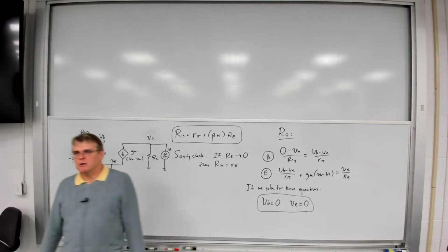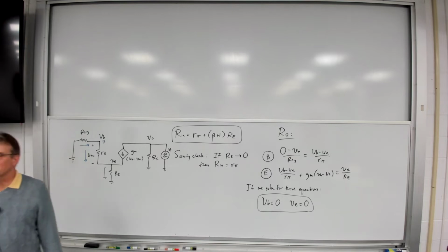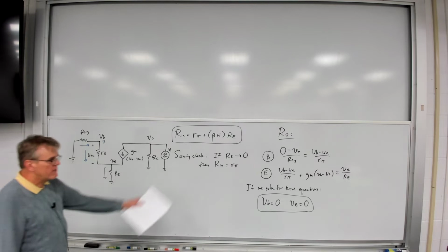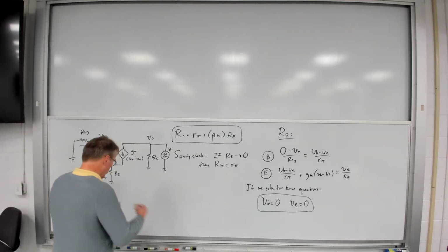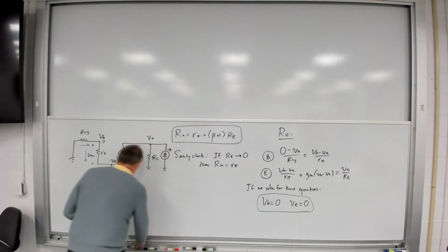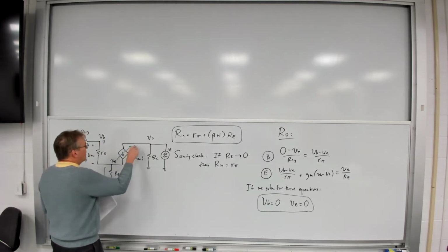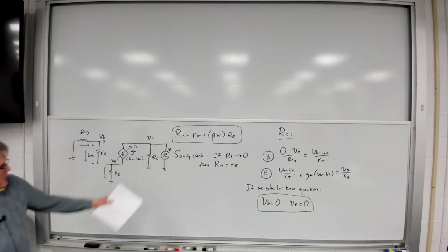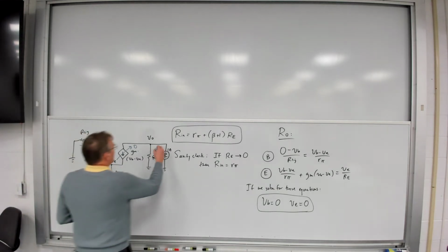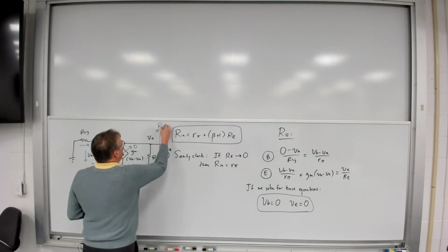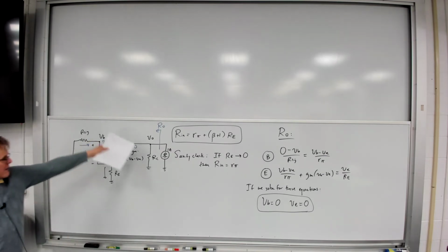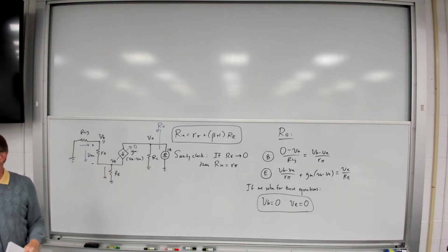So solving for those two equations gives us a rather interesting result, that both of those small signal voltages are just 0. And if that's the case, if VB and VE are both equal to 0, then that dependent current source is equal to 0. So in this case, Ro is a trivial result. Of course, I could write the KCL equation using source driving, but really, clearly the output resistance is simply going to be equal to RC.